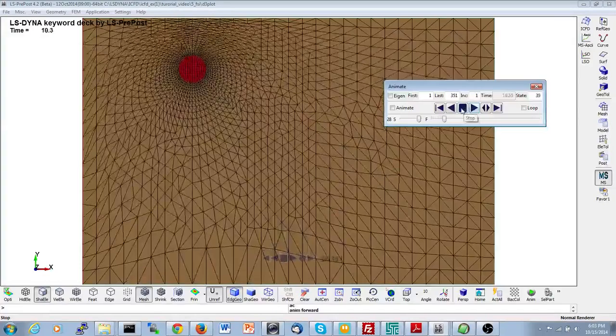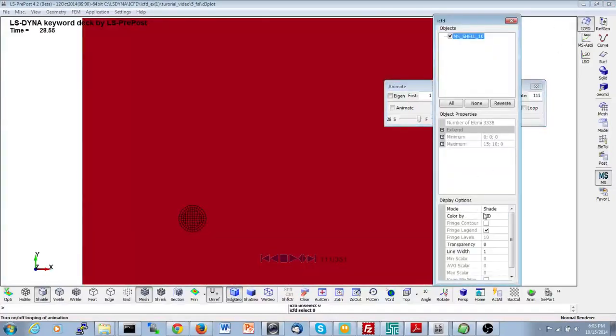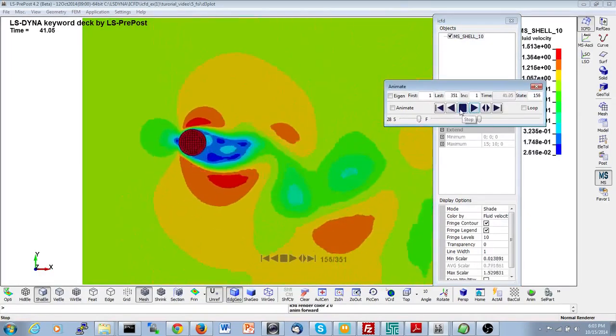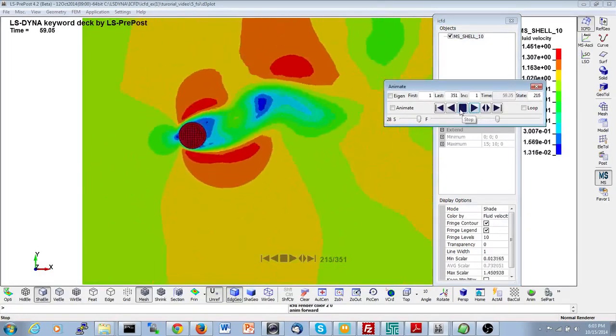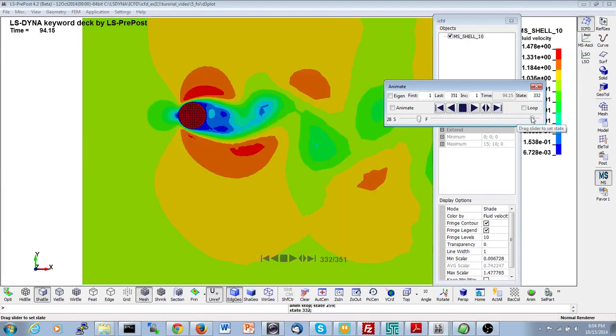If I do something like this, I get, as a result, something like that. When I try to animate here, and if I display the velocities, I can see that the fluid still takes into account the solid's movement, but if I look at the solid, it only translates in the y direction. There is no movement in the x direction. This is because the fluid now no longer has any influence on the solid. This would be a coupling direction 1.